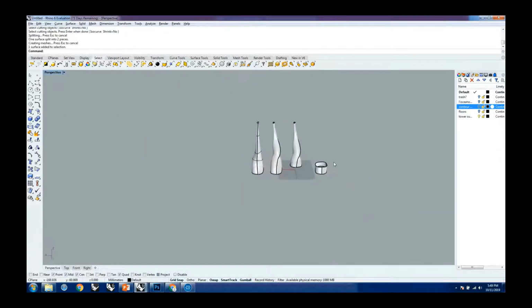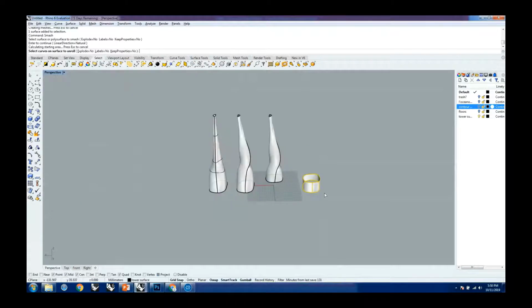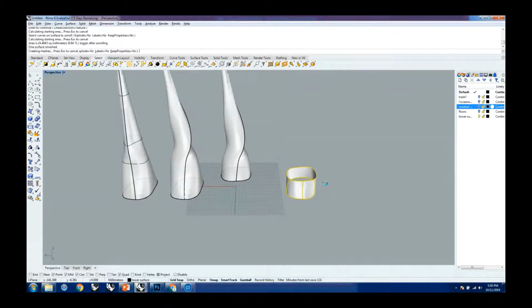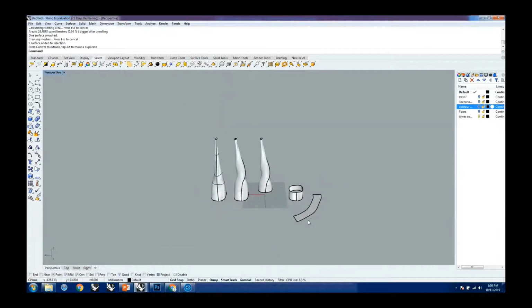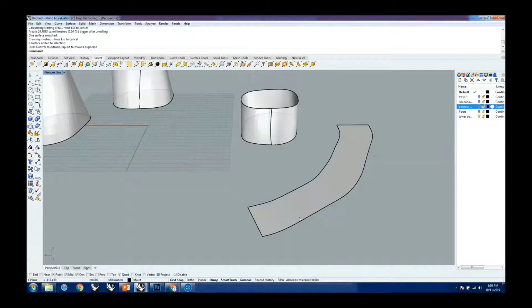And now we're going to follow the same process. And we're going to say smash the surface. And it doesn't matter if we explode it or not, because it's just one single surface. So now the problem is fixed, and now we can do whatever we want on this surface, and then we just take it back, flow it along this surface.